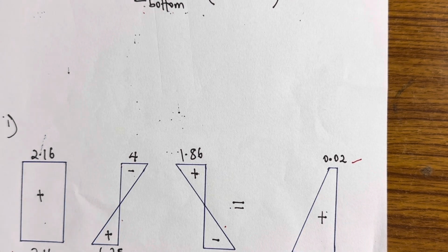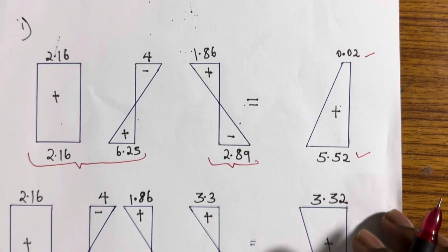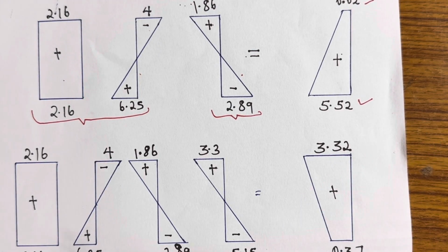Now I believe you have understood how we have found the resultant at both top and bottom. Now, let us also find for the second case. The second case is when we add, in addition to prestress and self-weight, live load again. So the diagram is this. This is due to the direct stress. This is due to the prestressing force. And this diagram is due to the dead load. And this one is due to the live loads.